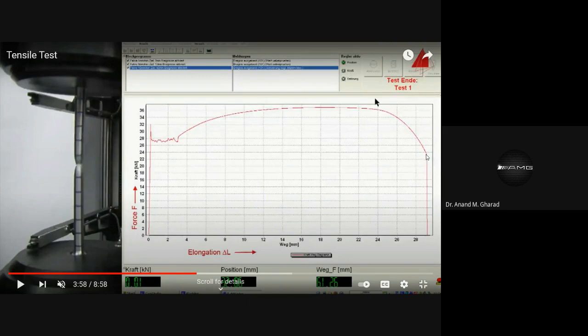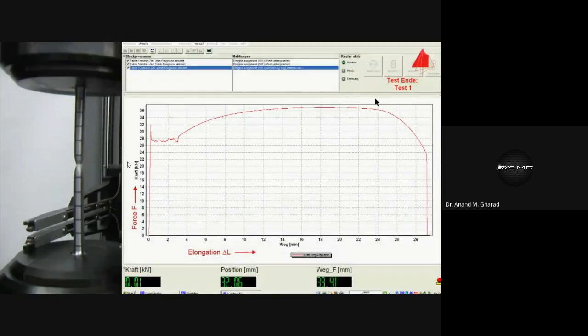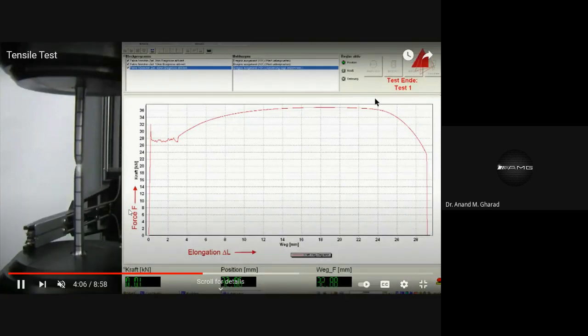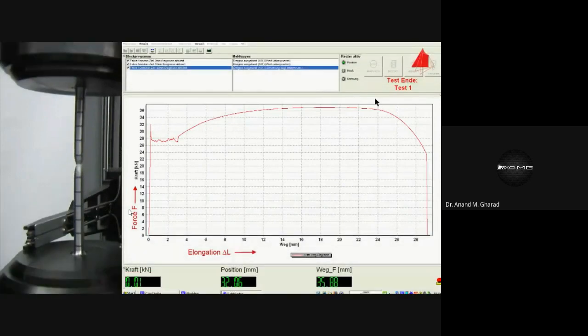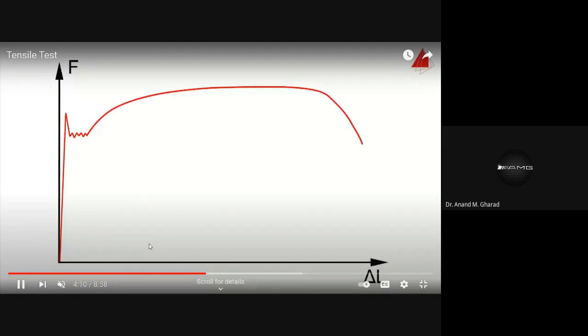This is known as the necking point. Okay? And after this is the post strain hardening area, right? So this is a typical explanation for the stress strain variation of a mild steel, and this is very, very important for our study. I have shown you this video purposefully. Just try to understand the various components.